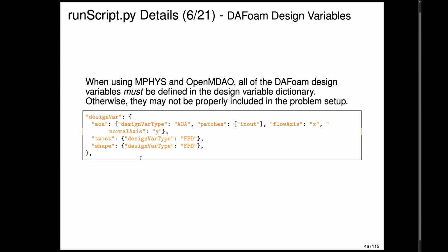It's critical that you define design variables here, because if they're not defined when passed to DAFoam as options, it's very likely that they will not be connected properly within your problem setup, which means that your case will simply not work. So always be sure to check that your design variables are defined within your DA options.